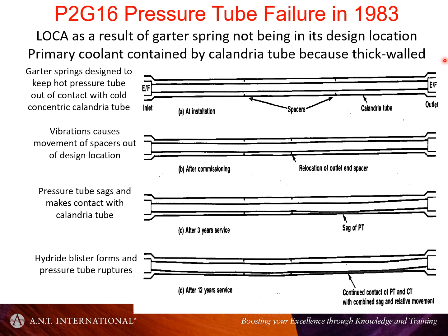So for many reasons, the irradiation properties of this pressurized component are extremely important to know, and that's why at ACL, over the lifetime of the calandria reactors, there's been a lot of effort expended on things like irradiation creep, because the component which is retaining the coolant pressure is sitting in the core. It's different from a PWR or a BWR because the pressure vessel in those reactors has a very low irradiation flux. It's basically outside of the core.